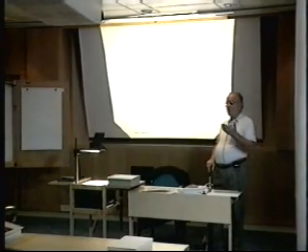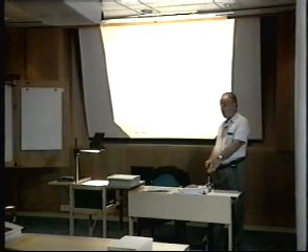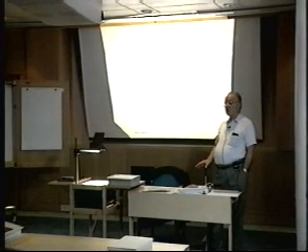And it turns out one of the papers I published, the isochronal testing of oil wells, has at least one example, which is in the book, where we ran an isochronal test of the initial discovery well of Ekofisk. And the whole concept is that I can express the rate equation for oil wells exactly like gas wells, exactly the same way, a difference in pressure squared relationship.